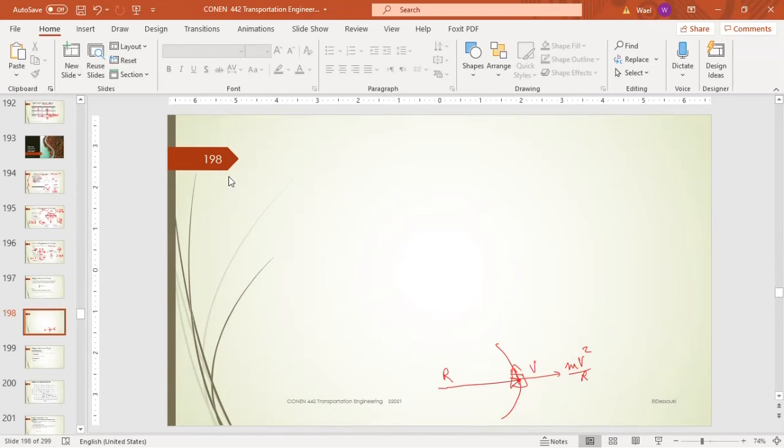That's the turning acceleration. So if we look at this vehicle, take a cross section and have a look at the elevation, we can see that the road, usually in horizontal curves, we make this super elevation. There is a slope in the pavement like this, and this slope is usually measured. This is alpha, and this is usually measured as 100, and there is E. That's the super elevation.